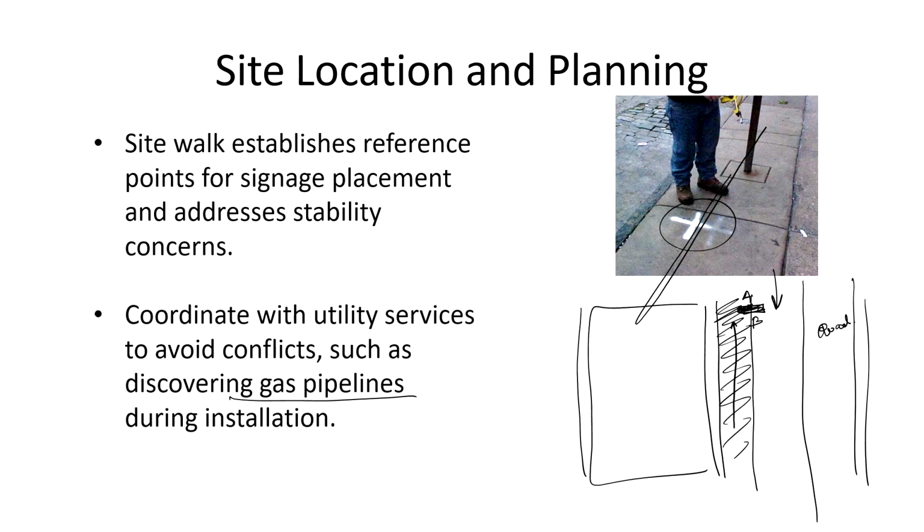We coordinated for the water pipe, gas pipe, even the landscape people who developed the landscape here. So, their water harvesting pipe, but we missed coordinating with one of the stakeholders, that was fiberglass. So, this resulted in the net facility being disrupted for more than 2 weeks.